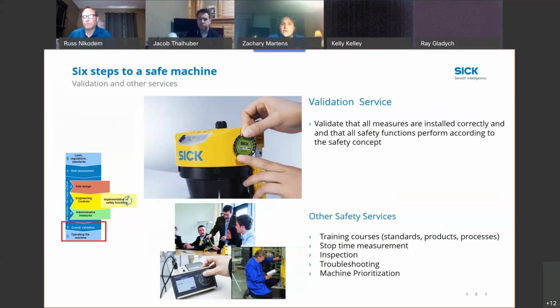Yep. That's part of it, and there's also the introducing of faults, right? We want to make sure that certain fault points that our engineering team defines before going out to site are checked, to make sure things are functioning in the way that we intended. They'll be checking the field. So if there's a safety scanner, making sure that it has the right mounting height, the correct resolution, those types of things, and the fields are set properly. Those all come down within the validation.